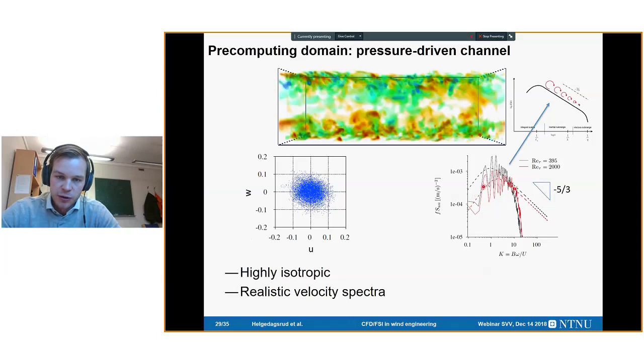And here we can also clearly see how the turbulence model works. It simulates the turbulence along here until we come to the unresolved scales, where the energy is rapidly dissipated. So this is sort of the highest wave number we have resolved in this simulation, and marks the upper limit. But we are mostly interested in low frequencies, so that's okay.